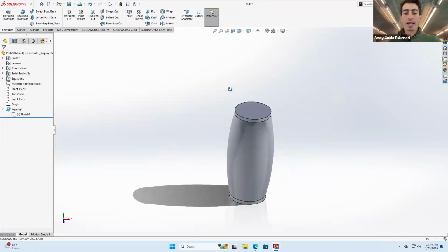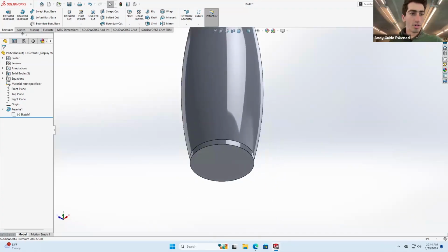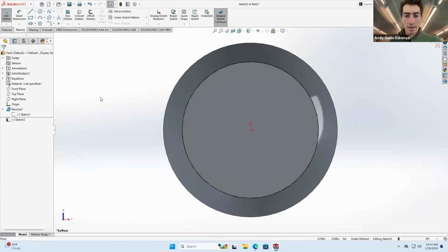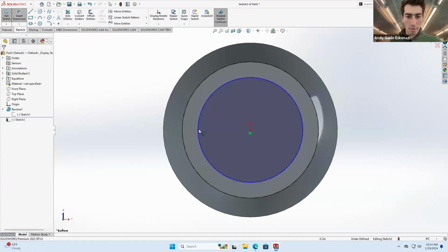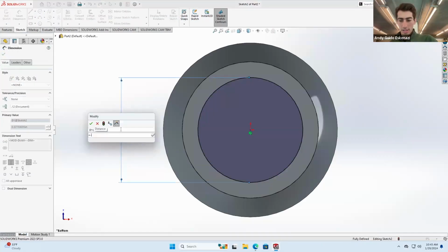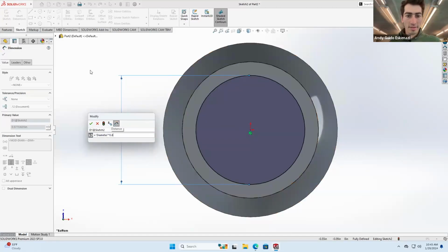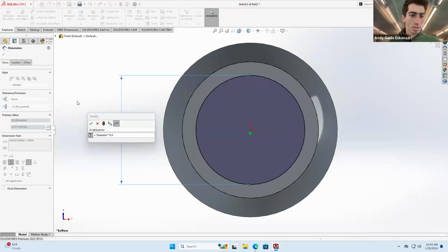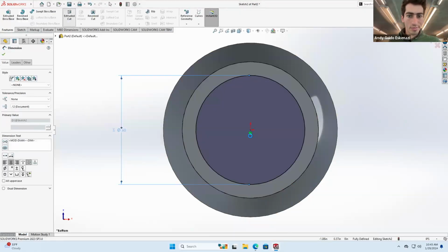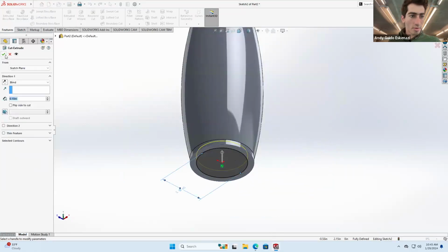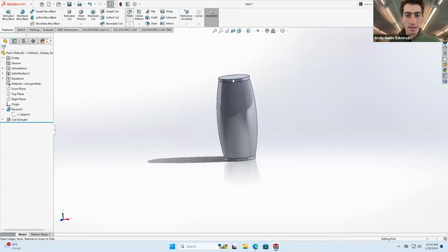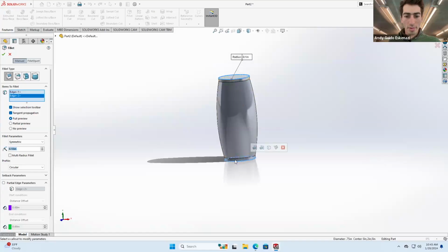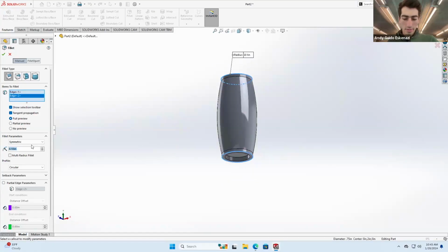There we go. And then we can add a couple of details, right, to make this look fancy, more like a screwdriver. For instance, in the model that I designed and put on the website, I did a little hole in here. And I said that I wanted that to be equal to the diameter times 0.8. And then I can do a little extrusion. Yeah, 0.1 is fine. Why not? And then I can do a little fillet both in the top and in the bottom of 0.05.